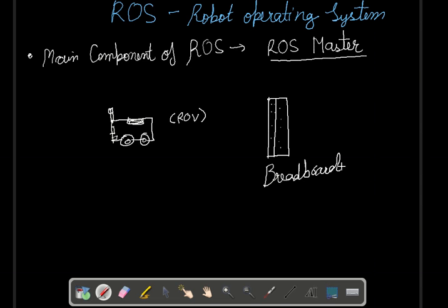What happens in the breadboard is that when you attach a wire, let's say here, which is of plus 5 volts, or any stream of data flowing through here, internally these are connected, so that if you read from this or this or this, you will get whatever value of data is being sent here.